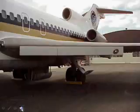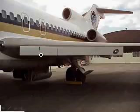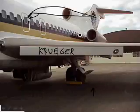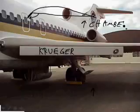Leading edge flaps. Here's a type of Kruger flap. A Kruger flap, if you look at it from the leading edge of the wing, just folds out, and it adds to the camber. The camber goes up, that's its biggest characteristic, and it does add a little bit of area.